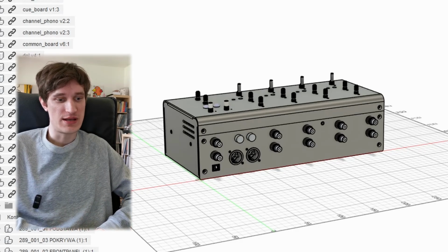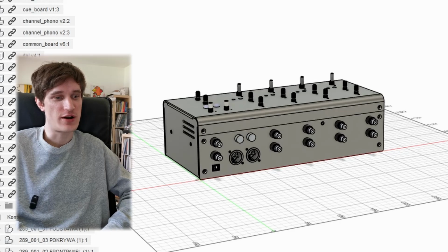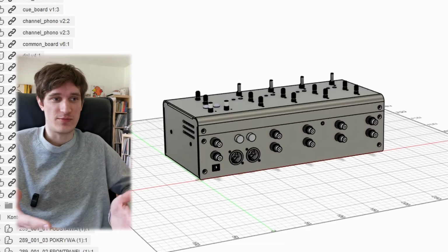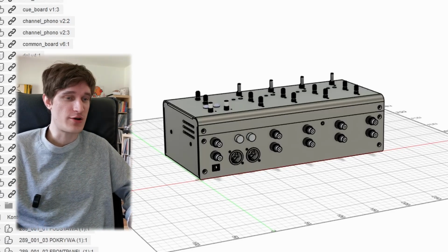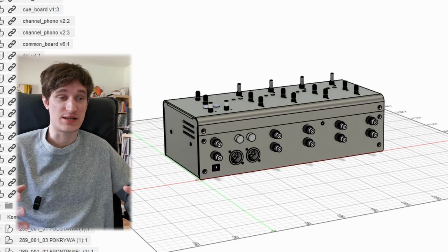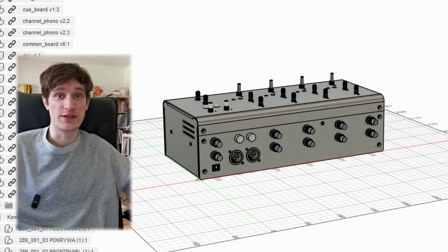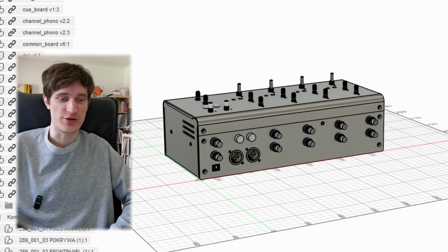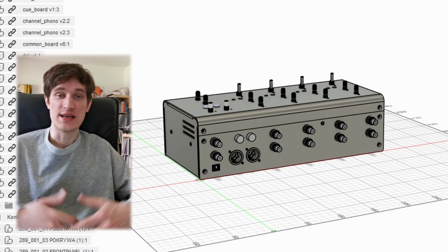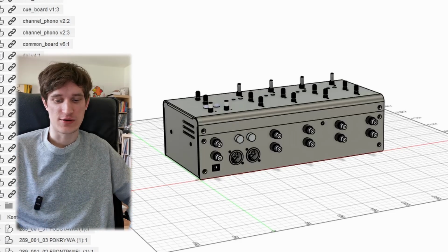Mainly it will be about grounding, because this is where a lot of confusion comes from, and this is where most problems arise. Due to bad grounding you can run into problems with catching interference, and with proper grounding you can lower the noise of your circuits. The most fundamental concept to understand to make a proper audio PCB is to treat grounds as signal return paths, and this is what we will also talk about with Eric.